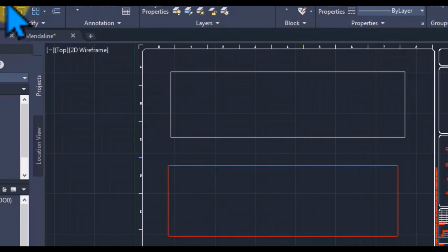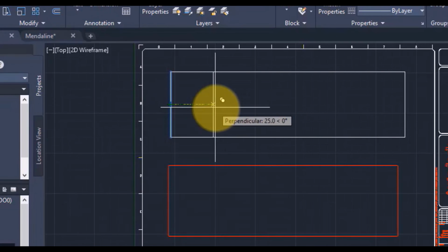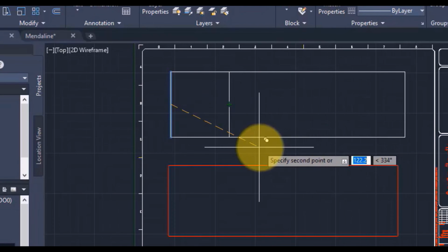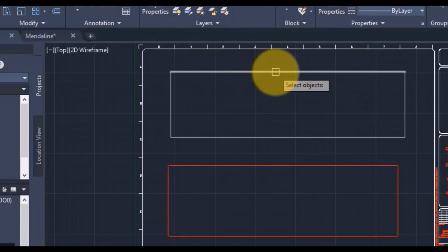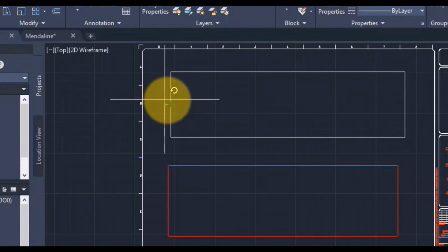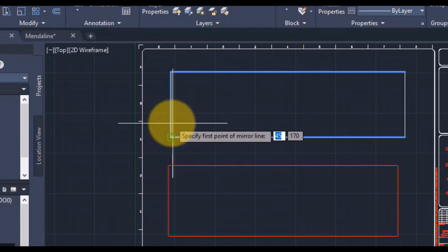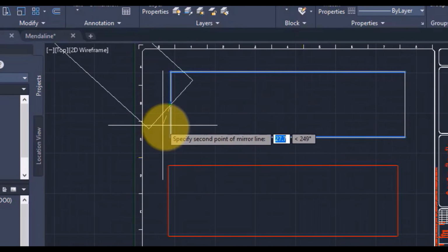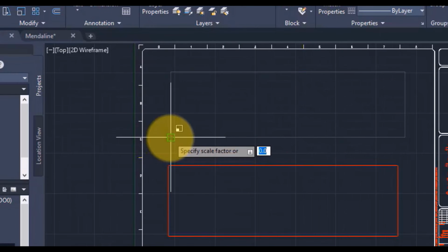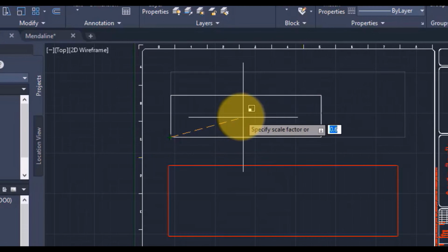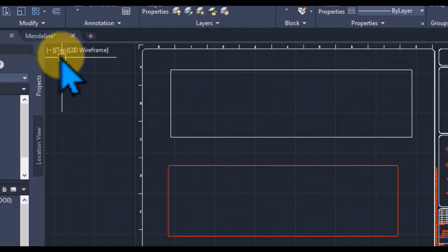Walk us through why. Standard commands operate on geometry. They don't know anything about the logic, the database. So if you use the standard delete command on a wire, you might leave behind these little connection dots, the T nodes, just floating in space, because the software didn't get the message to clean them up. And if you use standard trim, you break the line visually, but the database might still think those components are linked. Or worse, you create a null reference.